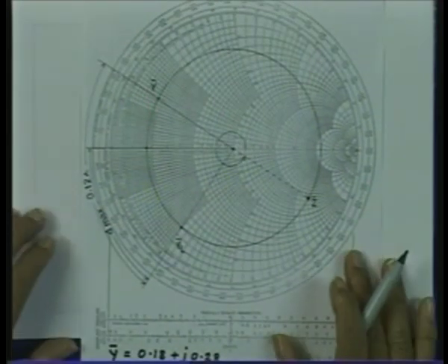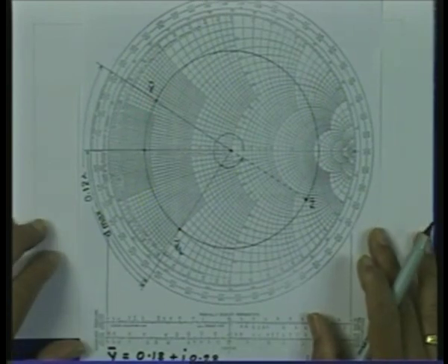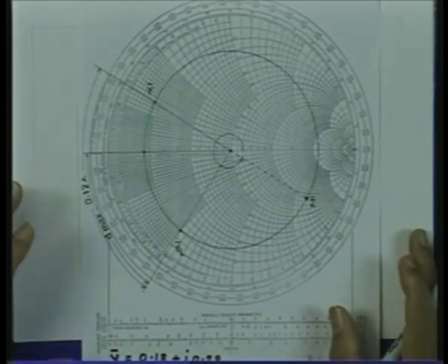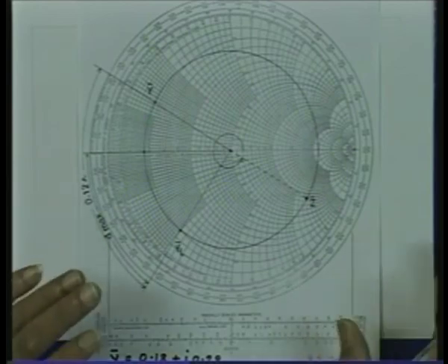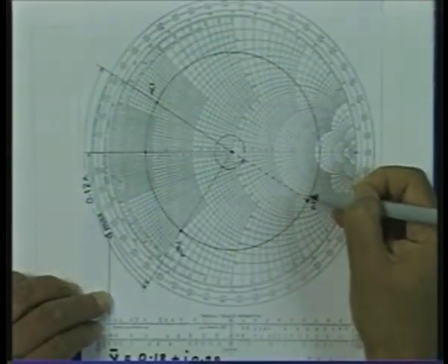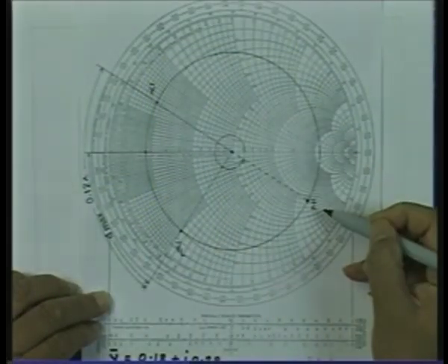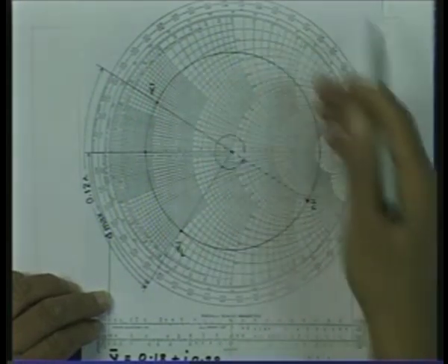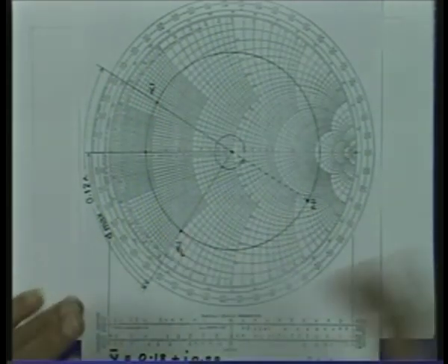So this problem clearly demonstrates the effectiveness of the Smith chart for switching over from admittances to impedances and vice versa. Even if some quantities are given as impedance or admittance, as the need may be, you may switch from impedance to admittance just by taking a diagonally opposite point on a constant VSWR circle and treat the Smith chart as the other Smith chart.